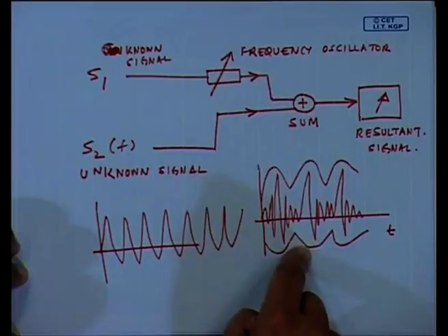Okay. And then finally, it will catch on to Akashvani hai. Okay. Because the frequency which you are setting is equal to the frequency of the received signal, and then they will match, and then you will hear the clear voice. But once you are very close to the station while tuning it manually, you will hear this signal which is waning and waxing because of the beating.